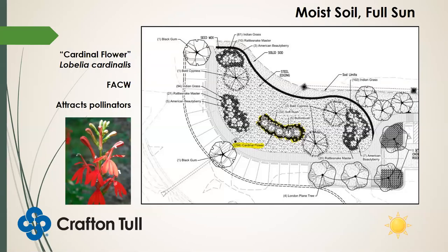Sometimes, though, if you have a network of bioretention cells for stormwater, you may consider which cell the water is flowing into first versus last. That first one's going to dry out much quicker than the last one. And you would have to estimate the amount of water you're expecting to be in there to know how moist that soil is going to stay throughout the growing season to know what species to put in there.